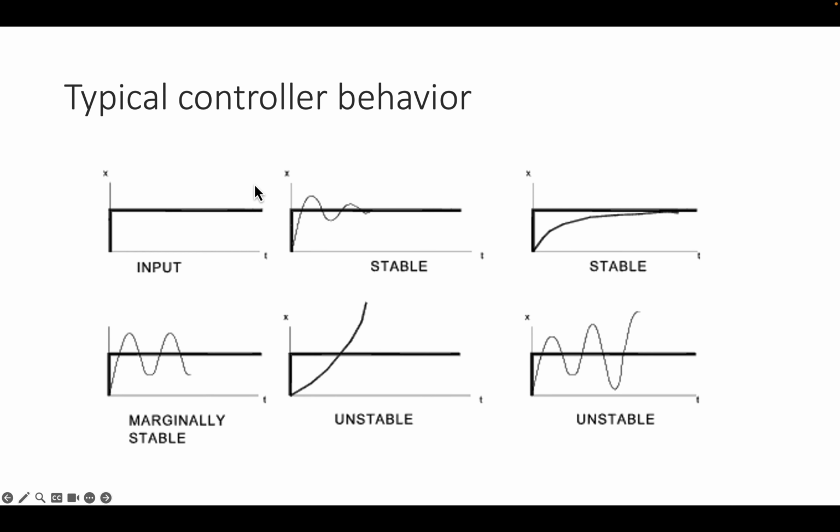So this is a picture that shows the different behaviors that I can expect. The idea is that the input happens at time 0, where I tell the robot the new goal. So the robot is currently here, but I want it to be there. And I'm now looking at the error as it evolves and as the robot approaches the desired set point. The first thing we've seen is some slow convergence toward the goal, toward the minimum of our function.